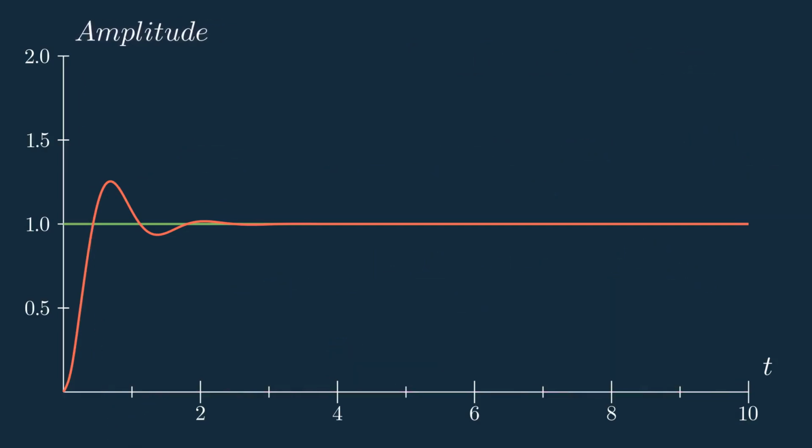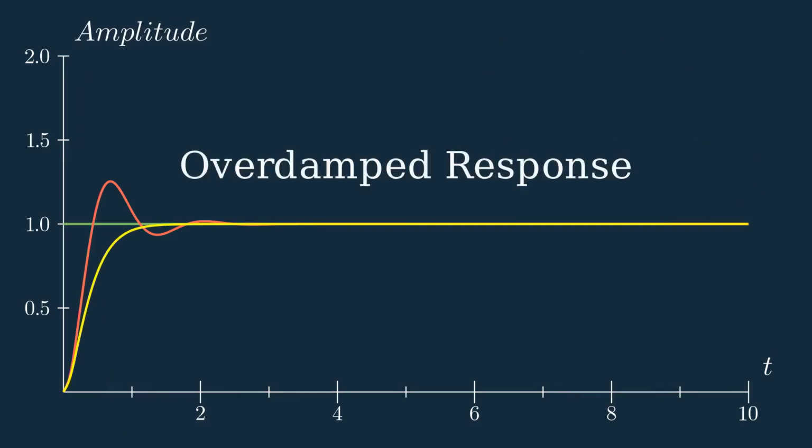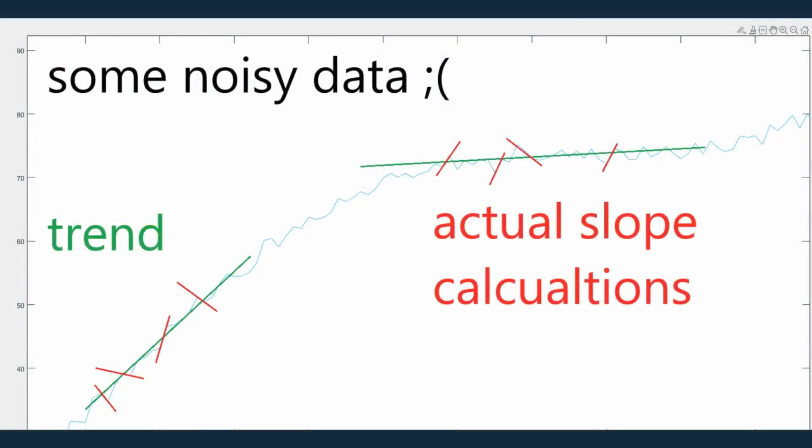However, two things to look out for. One is that if you overdampen the system, you might get a very slow rise time. The second thing to consider is very noisy signals will be amplified by the derivative gain, given the nature of numerical differentiation.